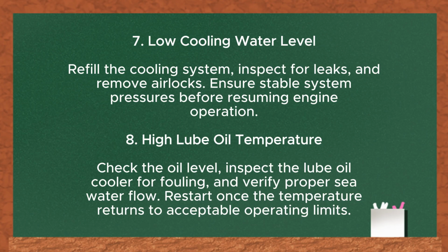And the 8th, high lube oil temperature. Check the oil level, inspect the lube oil cooler for fouling, and verify proper sea water flow. Restart once the temperature returns to acceptable operating limits.